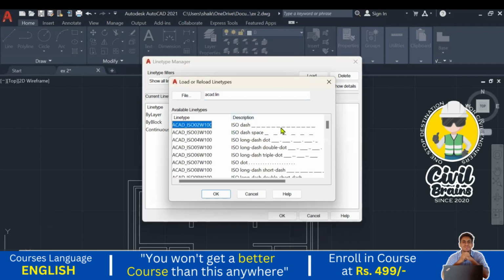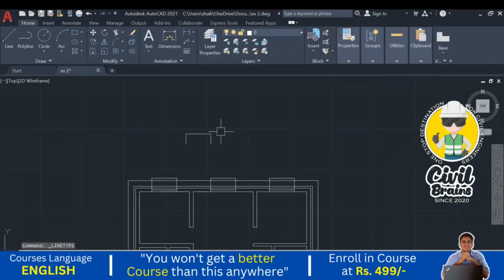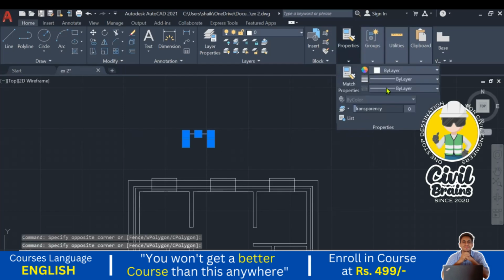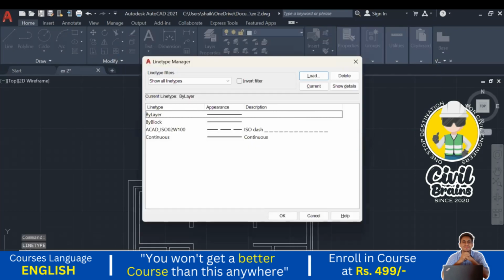Okay, we are considering the dash line only for the slab and chajja projection. These lines also have different meanings. Okay, so we are providing the dash lines. You just press OK. So dash line is loaded. Press OK. Okay, now, from where we want to do that, we need to select first. I just select this one as a sample. Select the object. Again, go to the property section. Go to by layer. Click on the dash line. Press enter. Okay, press escape.